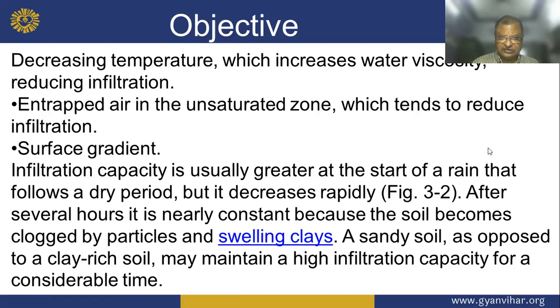So infiltration capacity is usually greater at the start of the rain, particularly after a dry period, but it decreases rapidly after several hours and becomes nearly constant because the soil becomes clogged by particles and swelling.